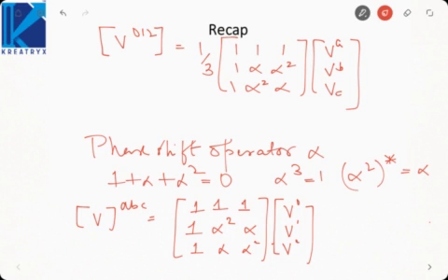And we saw that the line current zero sequence component is equal to IN by 3, and line voltage zero sequence component is always 0. That we covered in the last lecture.